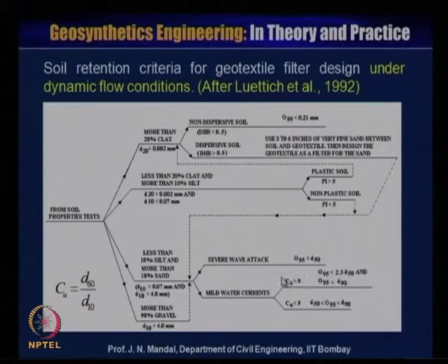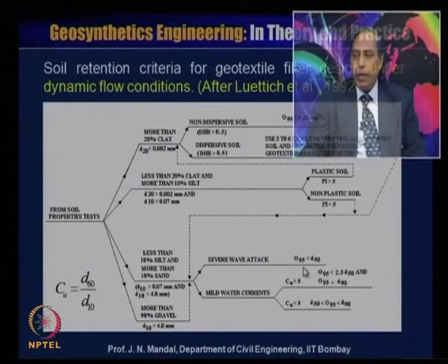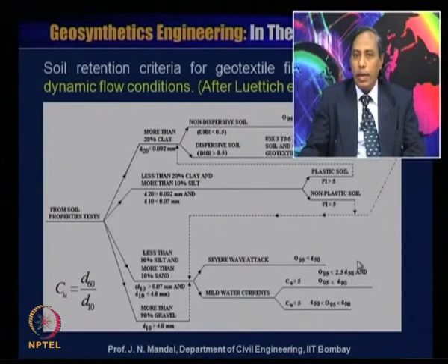Whether it is a severe wave attack, then O95 should be less than D50. If it is a mild water current, then Cu greater than 5 and O95 less than 2.5 times D50 and O95 less than or equal to D90. And if Cu is less than 5, then O95 is greater than D50 or less than D90.